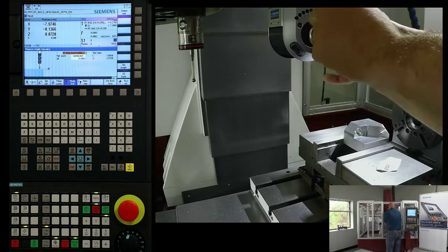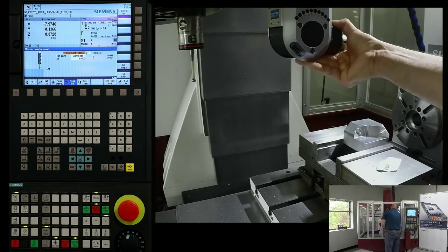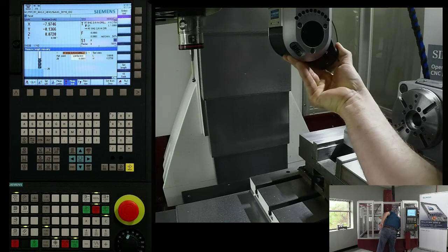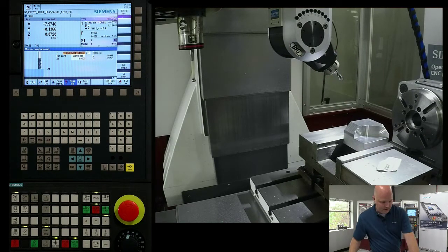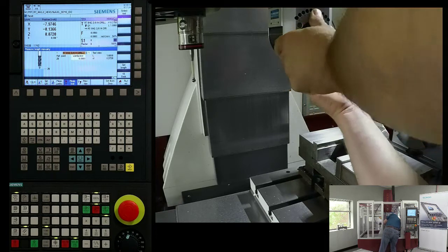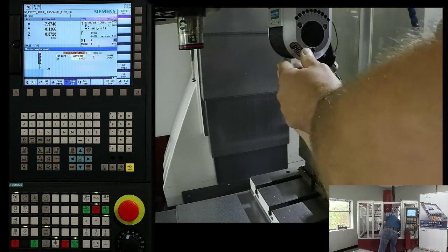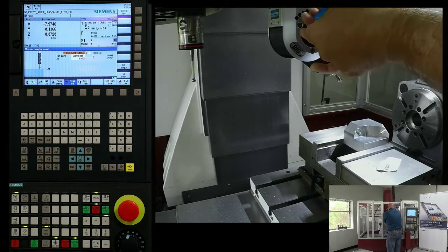This one, I like to try to get it as close as I can. So I'm backing out the set screw like before. I'm going to rotate it down. And I will be honest, the eyes aren't what they used to be, so I'm going to grab my cheaters here. All right. Looking at the bottom, I get it within the scale. Now I have to make sure I go to the 5-degree mark because I want to get to 45 degrees. And this is what really gives me that precision.